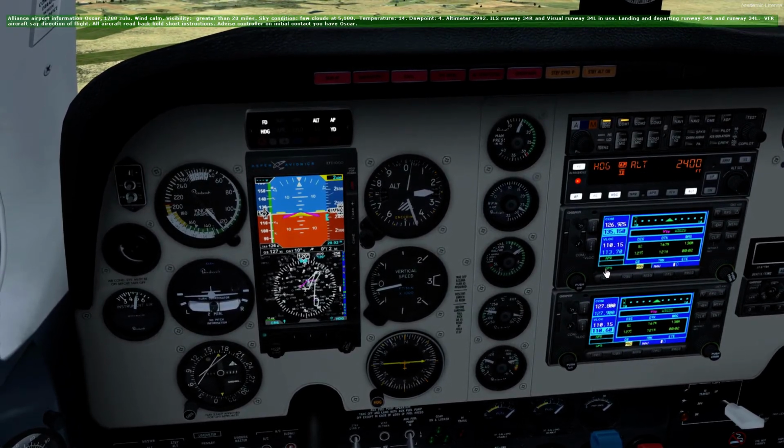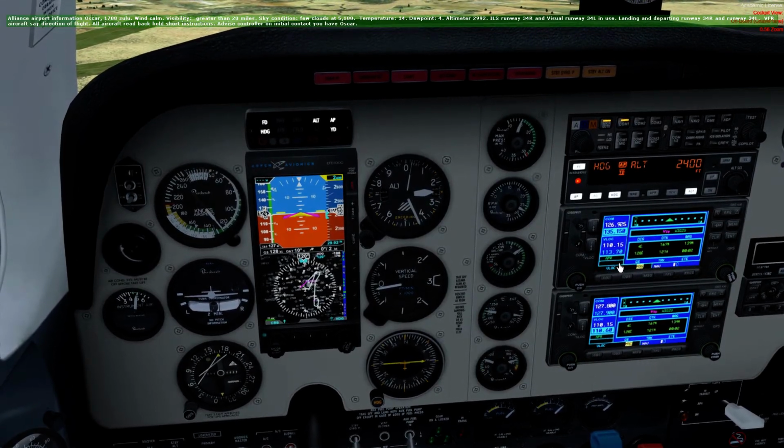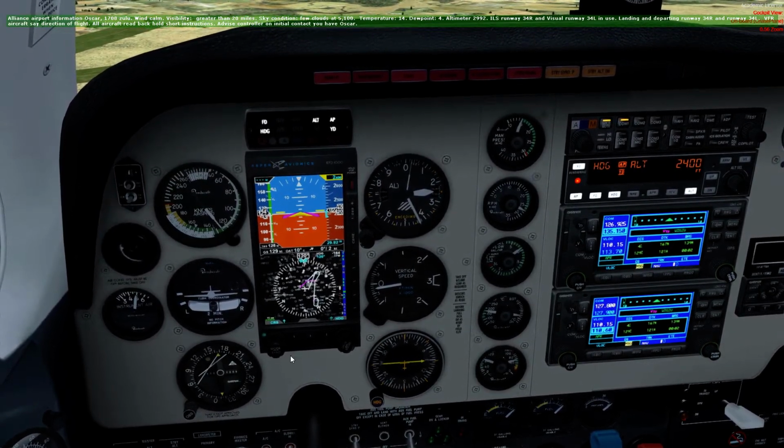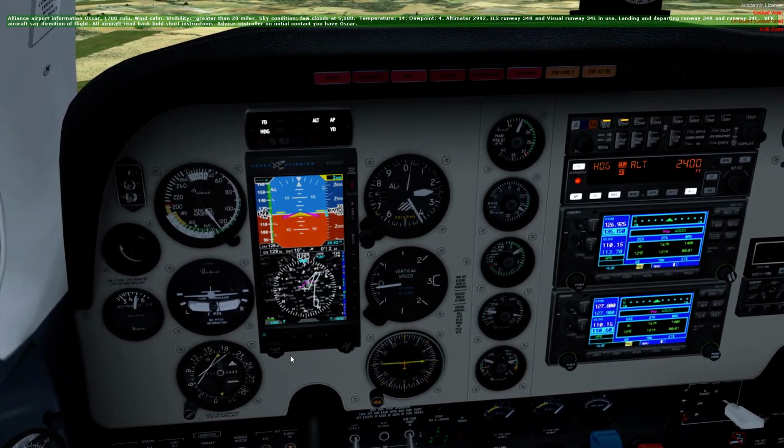It is important, if you're flying with a Garmin 430 or something similar, if your CDI button is set to GPS mode, you push this and set it to localizer mode. Otherwise, you won't capture the ILS frequency. So it's always important that you set that.